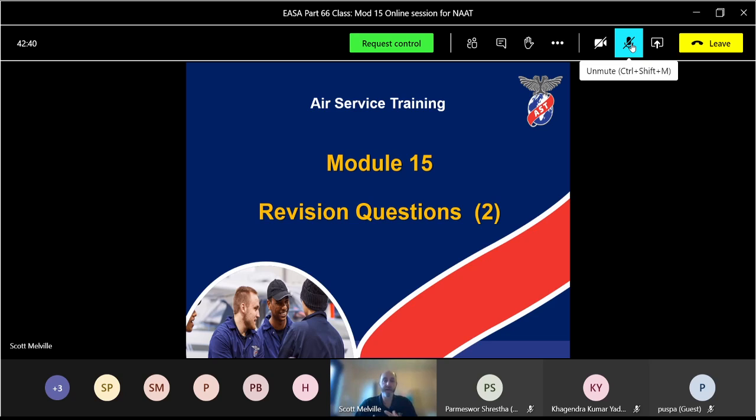Just in case. The discharge resistor, like I mentioned before, is there so that once you disconnect your LT lead, it will discharge to earth the power stored in the HIU within about 30 seconds. So that's why we give a minimum of 1 minute for a surface gap igniter and a minimum of 3 minutes for an air gap igniter.